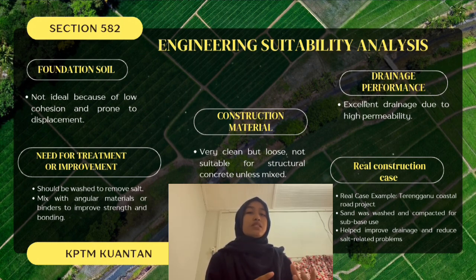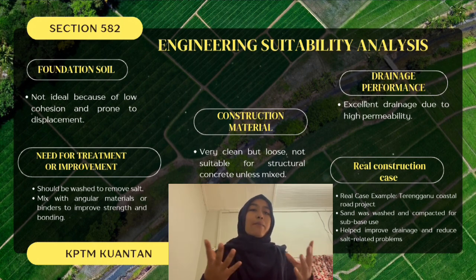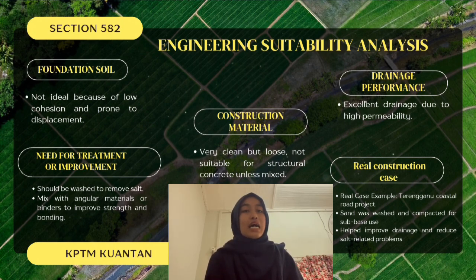Before using beach sand for construction, some treatment is needed. It should be washed to remove salt and sometimes mixed with angular materials or binders to increase strength and bonding ability. Lastly, a real constructed example is from Terengganu.